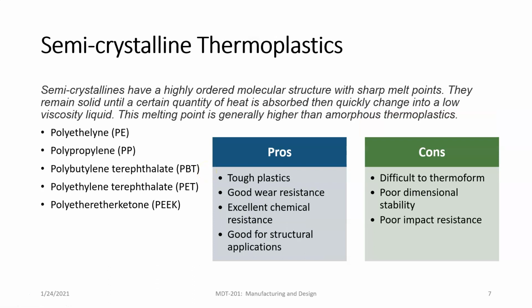Now looking at semicrystalline thermoplastics, these are highly ordered molecular structures with sharp melting points. They remain solid until a certain quantity of heat is absorbed and then quickly change into a low viscosity liquid. This melting point is generally higher than the amorphous plastics. All right.